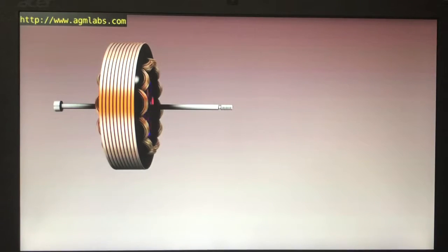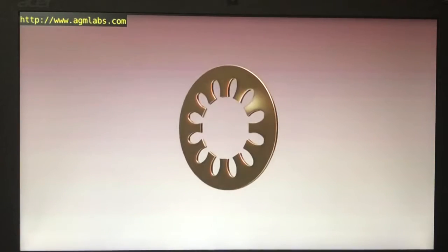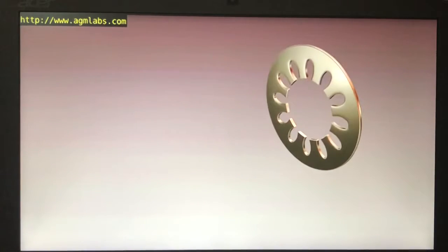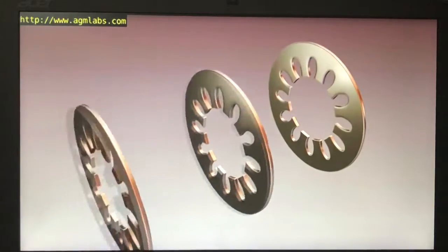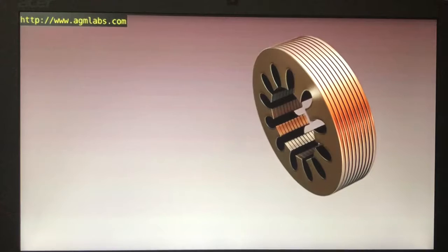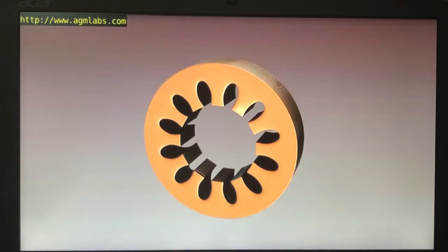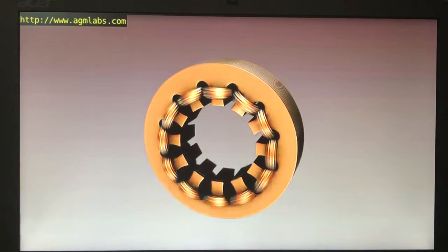An AC induction motor has two basic electrical parts, a rotor and a stator. The stator is the stationary electrical component. It is built by putting together iron layers forming a group of individual electromagnets arranged in such a way that they form a hollow cylinder with one pole of each magnet facing forward. The center of the group of magnetic poles is built by winding insulated copper wire clockwise and anti-clockwise. The coils are wound in such a way that when current flows in them, one coil is a north pole and its pair is a south pole.